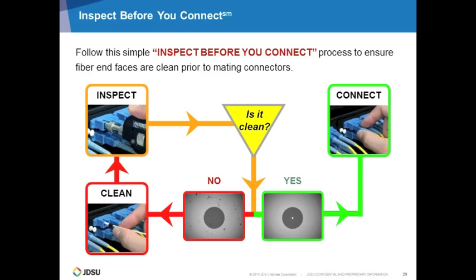Well, several reasons for that. First, what if you have a clean connector? Then you're using the cleaning tool and basically wasting the cleaning tool. Second thing, no cleaning tool is ideal, meaning that it can introduce contamination on the fiber, and the only way to verify that is by inspection.